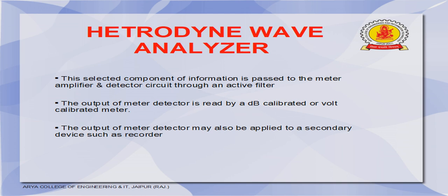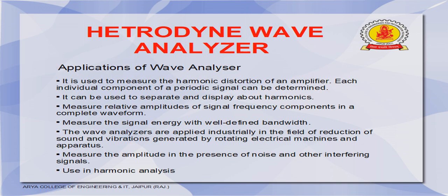So in this way, we can choose a particular wave analyzer based on the frequency of the signal that is to be analyzed. Accordingly, if we want the audio frequency range, then we select the frequency selective wave analyzer, and if we want the radio frequency range, then we select the heterodyne wave analyzer. So this is about the different types of wave analyzers.